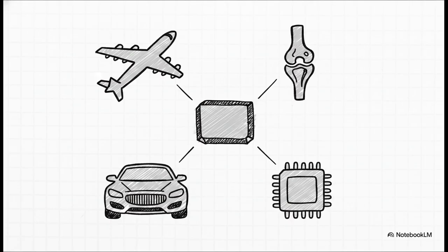See, all of these micro decisions on the lathe map directly to things we rely on every single day. Different industries prioritize completely different operational characteristics based on where that finished component is going to live. Aerospace needs supreme strength-to-weight ratios to reduce fuel consumption on planes, so they lean heavily on 7075 T6 aluminum and titanium. The medical industry needs non-reactive properties for human implants, so they use 316L stainless and titanium grade 5.